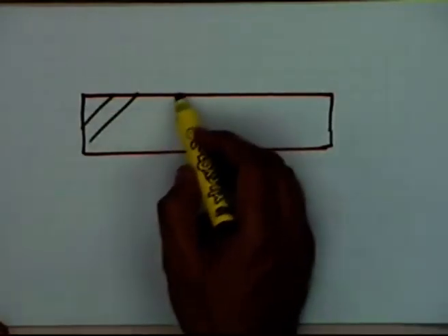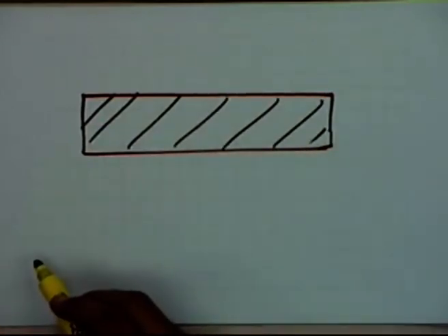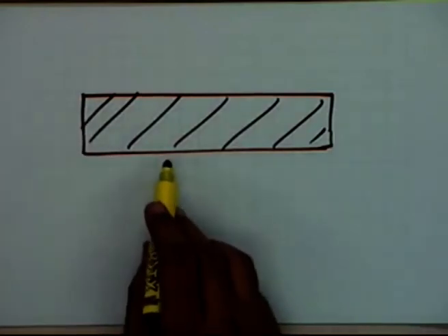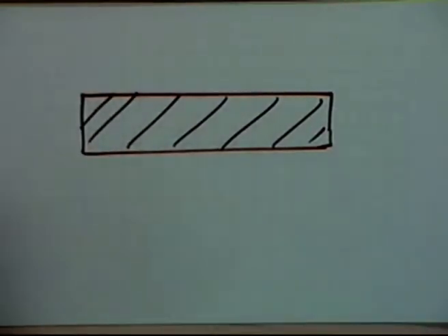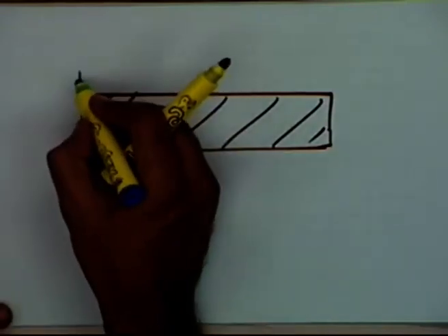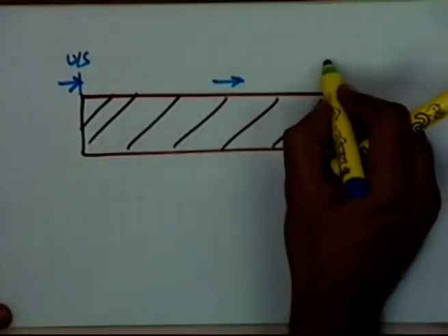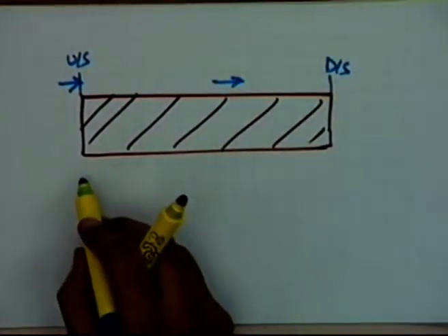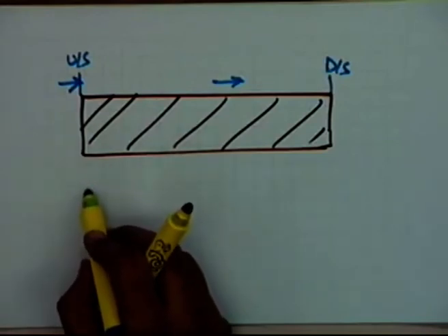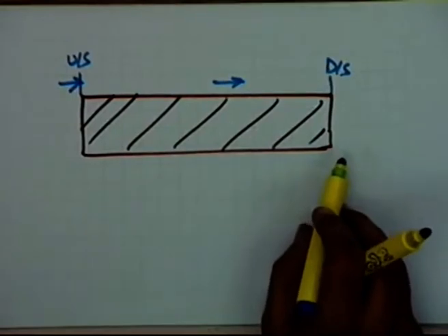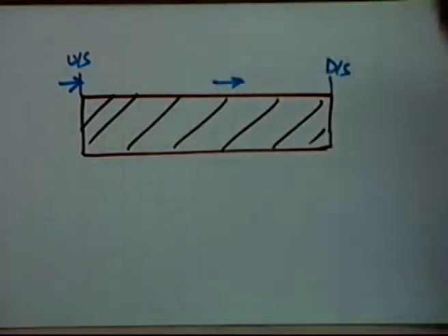We wanted a uniform distribution over this whole area, and in the surface irrigation methods we have seen that we cannot achieve this because the water flows from the upstream end to the downstream end, and that's why there is uneven distribution, because the upstream end segment of the field gets more water than the downstream end. So this can be avoided with this sprinkler irrigation method.